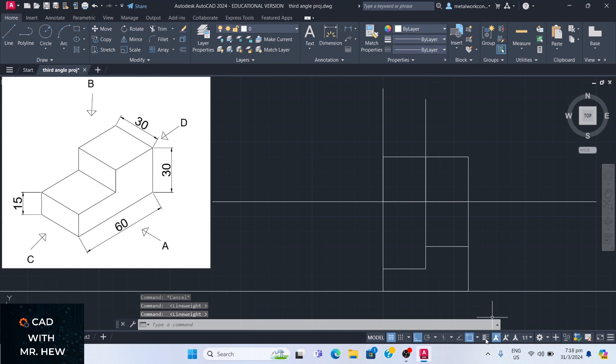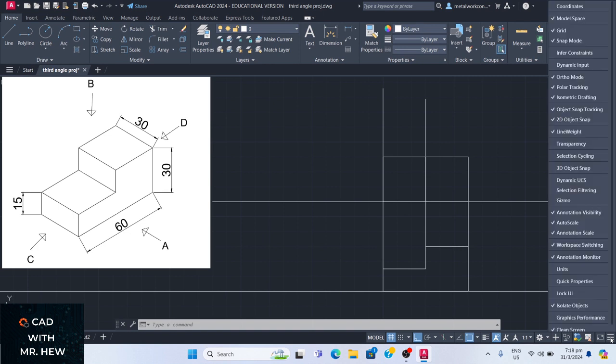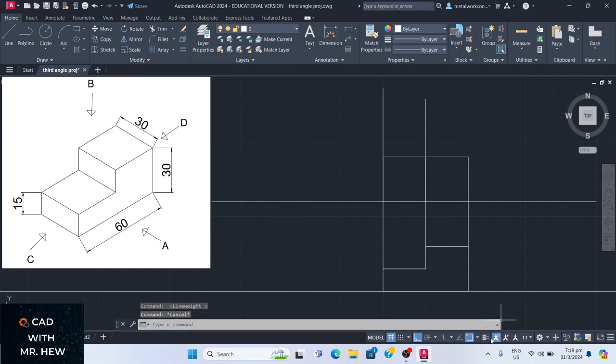We're going to come down here and show the line weight display, right? If this icon is not here, then you come down to this icon, which is customization. You come up here, go up to line weight, and make sure that it is checked, right? So once it is checked, then it will show up down here, right? So we press in the workspace again. If I click this line show line weight, there is the object shown with the line weight of 0.3.